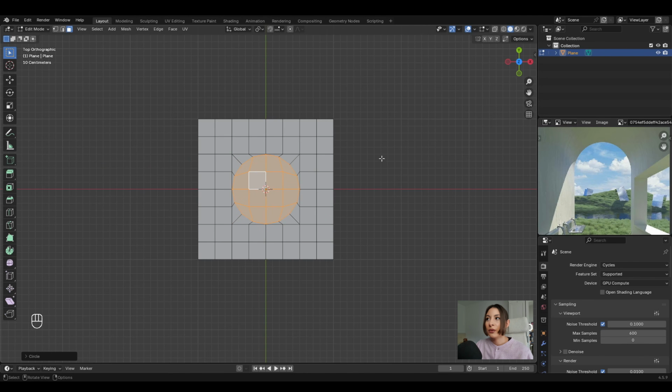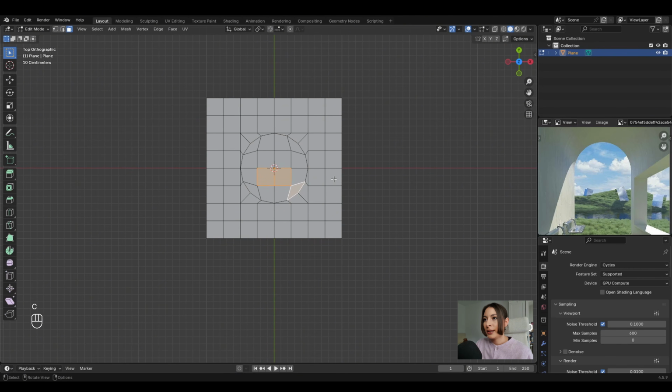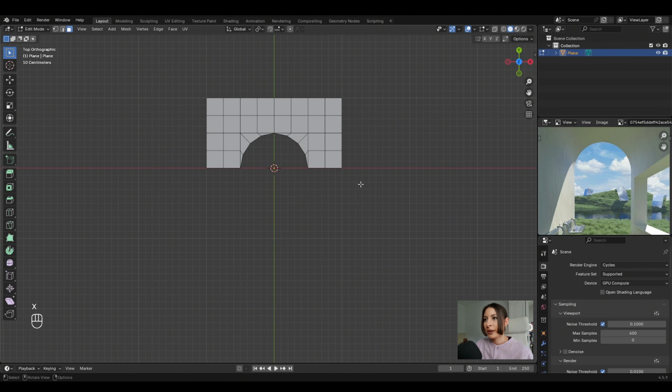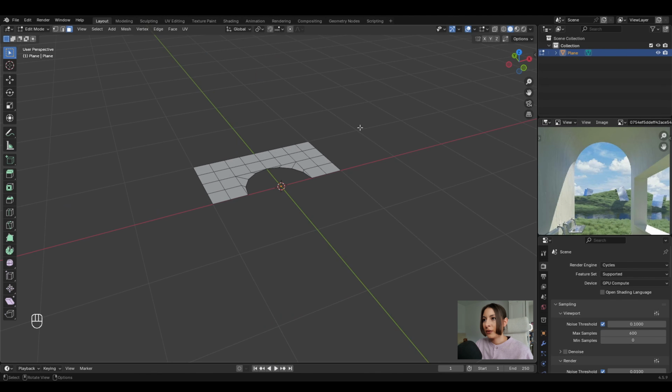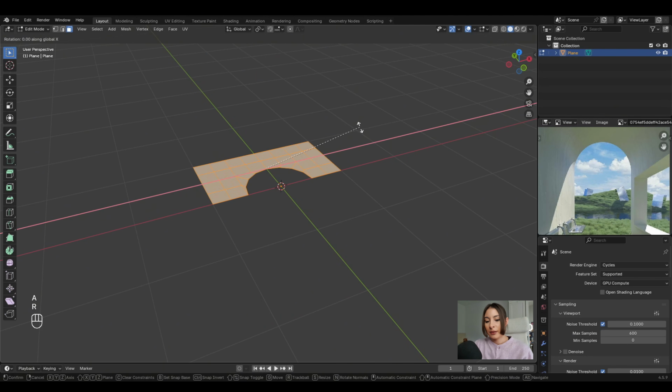And you have to activate your loop tools up here under edit and preferences and loop tools. And let's go to our circle select with C. And we can select these faces here and faces. Next we can rotate this whole thing. So select everything and R X and 90.